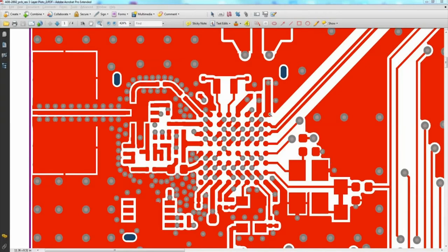An electrical circuit must always be a closed loop. Up to now, only the signal path was discussed, but not the path back to the source: the return current, as it's called. With DC, the return current takes the way back with the lowest resistance. With a higher frequency, the return current flows along the lowest impedance, and this is directly beside the signal.